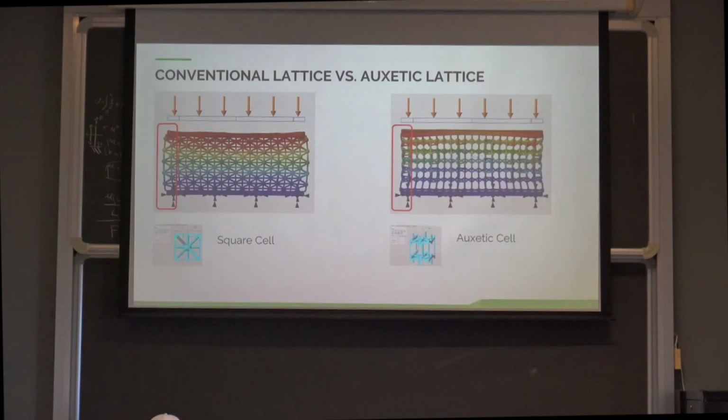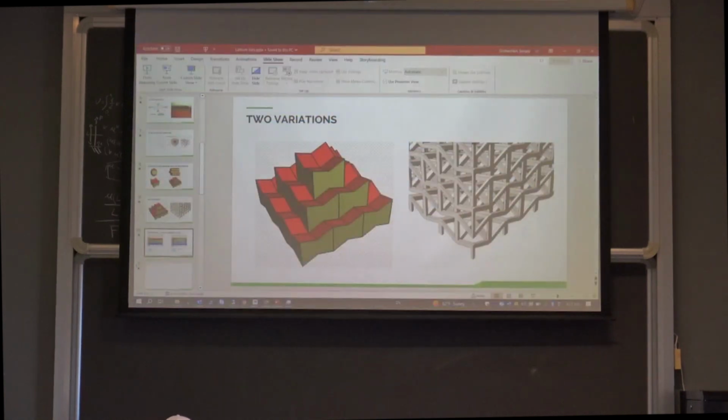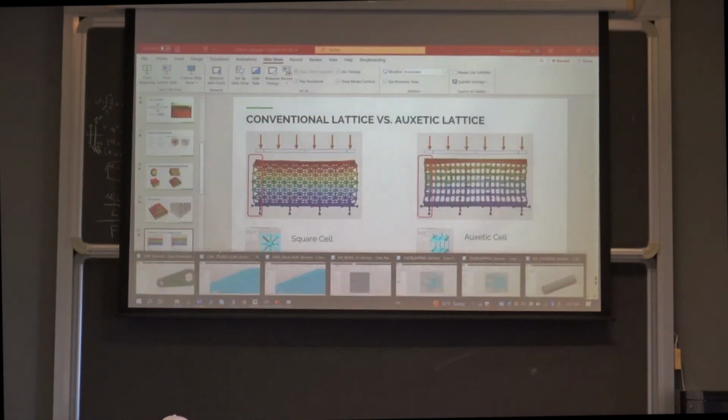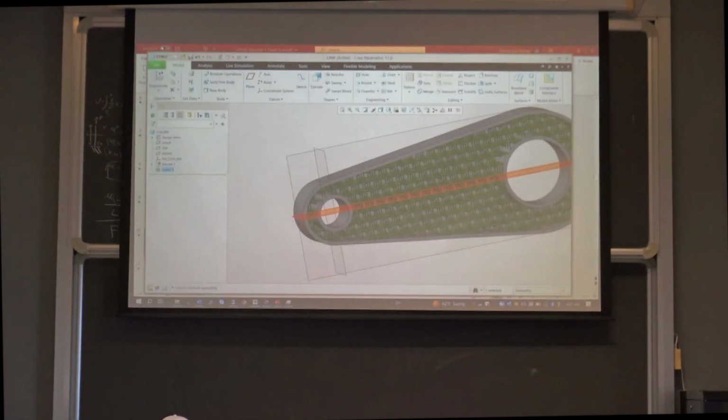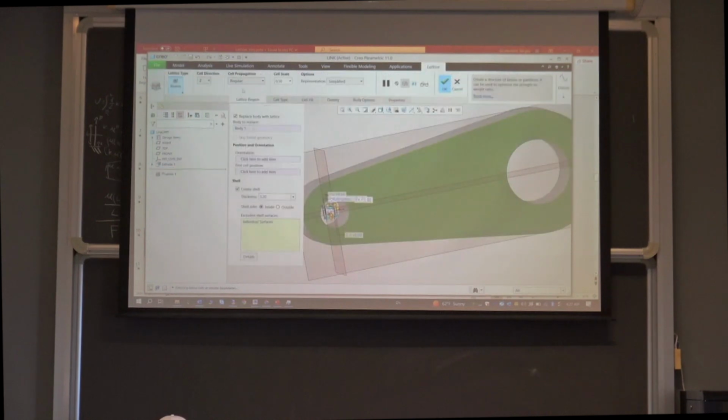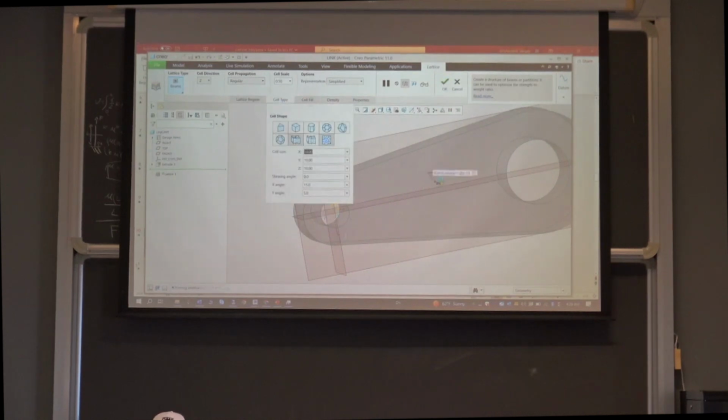Now the last pattern in this gallery. So back to Creo. Edit Definition. Our last pattern is stochastic lattices, this one. Stochastic lattices are very important. Usually they're based on Voronoi decomposition of space. And cells in this case are convex polyhedra of random size and random shape.